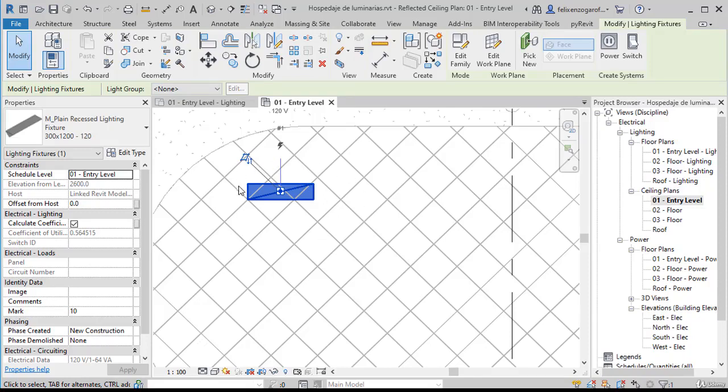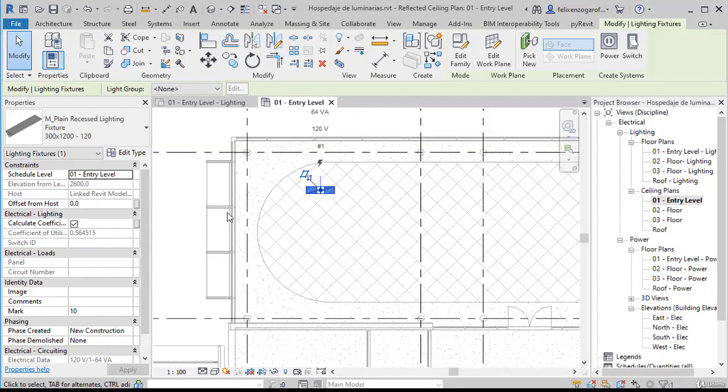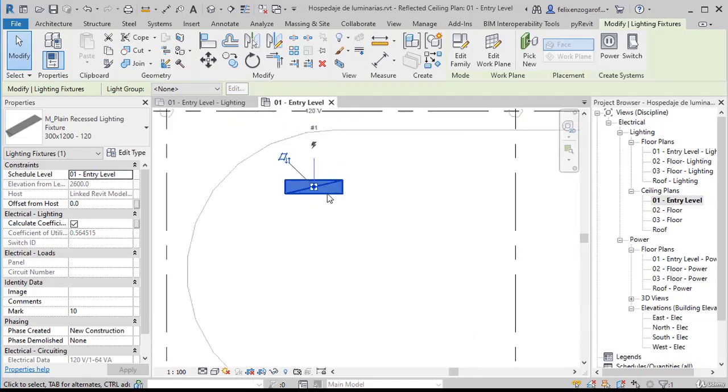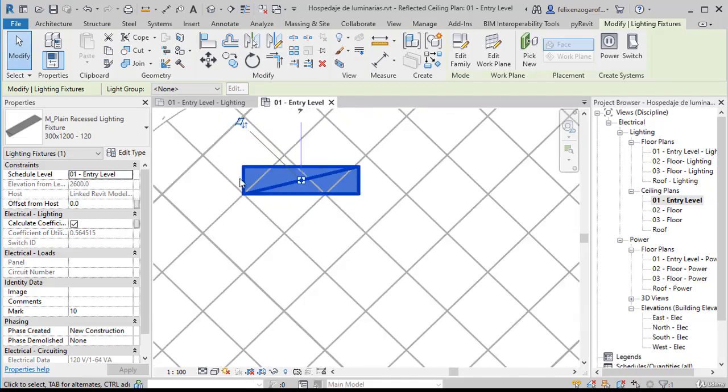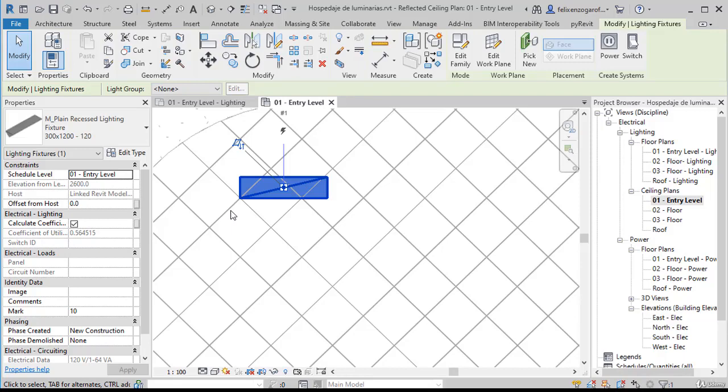When we place a luminaire, no hole has been generated in the ceiling because we're working on a link. We connect architecture externally. But when the luminaire is placed directly on the ceiling element of the architectural model itself, we'll generate a hole, and when we try to place the luminaire, in the case of the lighting project, we'll find the space unusable. We cannot place luminaires because the ceiling has a hole made by the previous luminaire placed by the architect. These are the kind of details that we should coordinate to avoid problems in the future.